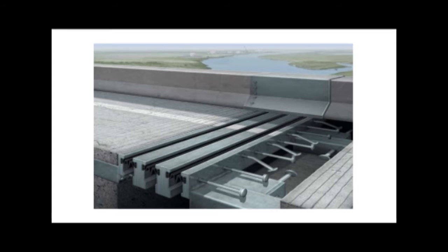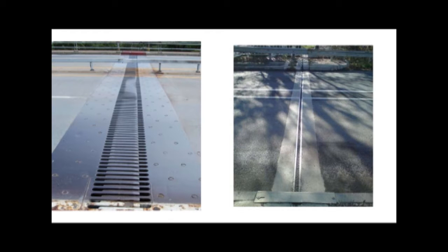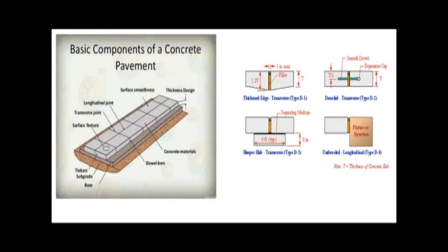So if one is driving on the bridge road, one may suddenly receive a bump, like the vehicle gets lifted a bit, but then one wonders, what is it? It's actually the place where you have just moved over the expansion gap. The second thing is the contraction joint. Contraction joint is usually in the slab, so it is provided with the help of dowel bars or longitudinal bars that are properly assigned in a longitudinal or transverse direction. What happens is that if contraction occurs, they still hold the two slabs together.